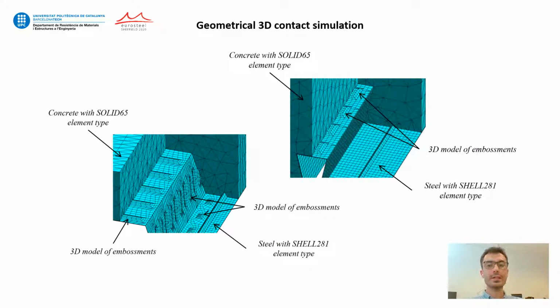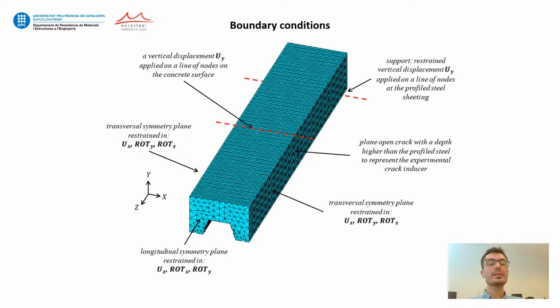Therefore, the interface of materials consists of three-dimensional contact elements with complex geometry. To allow the contact elements to slide and detach with no restriction, standard unilateral contact behavior is selected. The coefficient of friction is 0.5 in the case of galvanized steel and 0.1 for stainless steel. Due to the symmetry conditions, only a single half-rib of the slab is modeled.